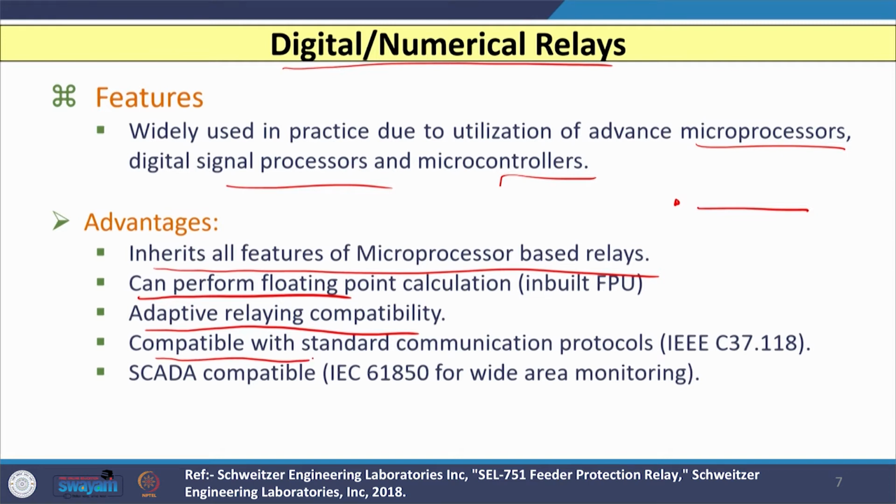These relays are compatible with the latest communication protocols, that is IEEE C37.118, and they are also SCADA compatible. This relay is also compatible with IEC 61850 substation and automation protocols, and these protocols are widely used in wide area monitoring, control, measurement and protection purposes.